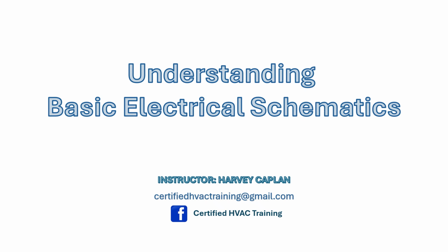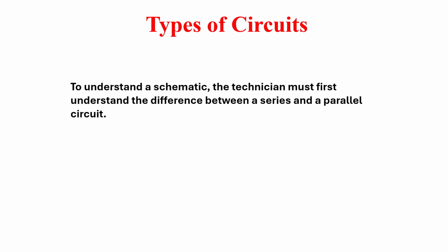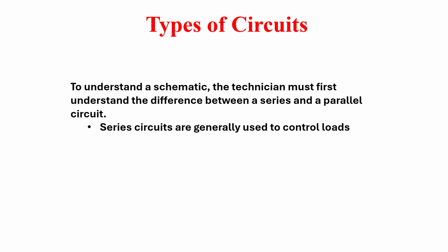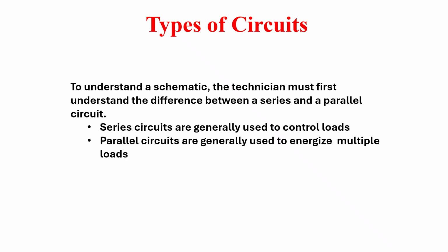In this video, we will begin to understand and use electrical schematics. To understand a schematic, the technician must first understand the difference between a series and a parallel circuit. Series circuits are generally used to control loads. Parallel circuits are generally used to energize multiple loads.